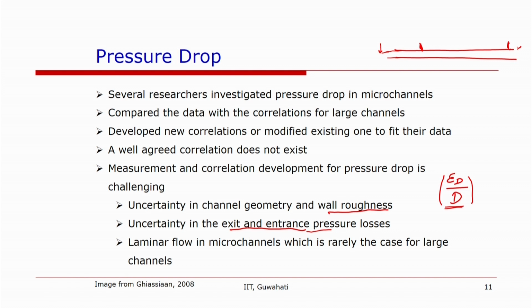Then it is also not possible to immediately extrapolate the correlations developed for large channels, because the flow in large channels is often turbulent, whereas the flow in small diameter or microchannels is often laminar. So it is not possible to use the correlations for large diameter channels as they are for small diameter channels.